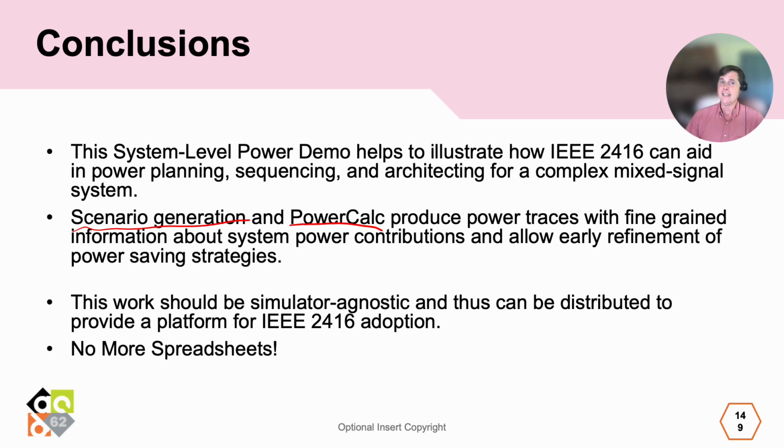This system that we've put together is simulator agnostic. It doesn't use any specialized code from any vendor, and therefore we can easily distribute it to anyone. It won't necessarily work on every single platform, but we should be able to distribute it, and it should be easily adapted into any vendor's simulation, as long as they can co-simulate SystemC and SystemVerilog. And if there's anything that you get from this tutorial, it should be this: no more spreadsheets. We really need to start building our power modeling tools to make use of IEEE 2416 instead of these error-prone techniques that we're so used to.